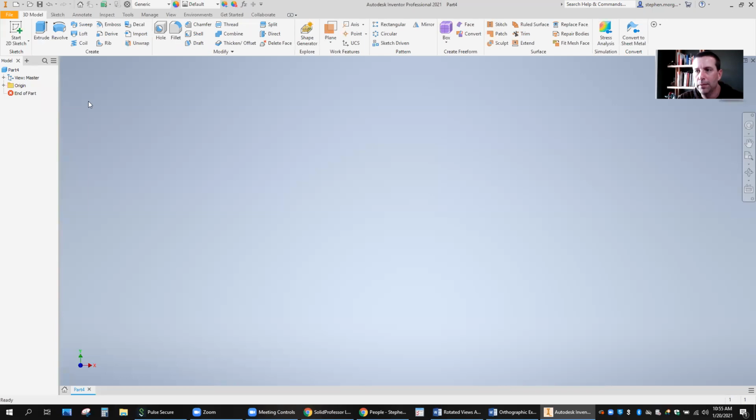And I'm going to begin my tutorial as if you've never used a parametric modeler before, so if you've never used SolidWorks, we're all on the same page. What I call this up here is the ribbon toolbar. That ribbon toolbar can change based on your tabs. These are the tabs up here. The two tabs you're going to use most often are the Sketch and 3D Model tabs. In SolidWorks, this is called Feature, and this is still called Sketch. But Feature and Sketch, or 3D Model and Sketch, are the two tabs that we'll be using pretty heavily for a while.